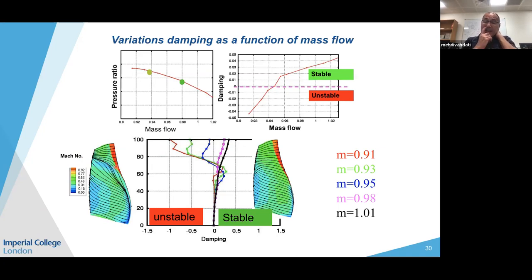But the problem is that when people want to design it, they design this area. If you notice, the problem comes from further down. If you want to redesign the blade, you really ought to redesign further down the blade rather than up here, because the mess up here is caused by what's happened down here.